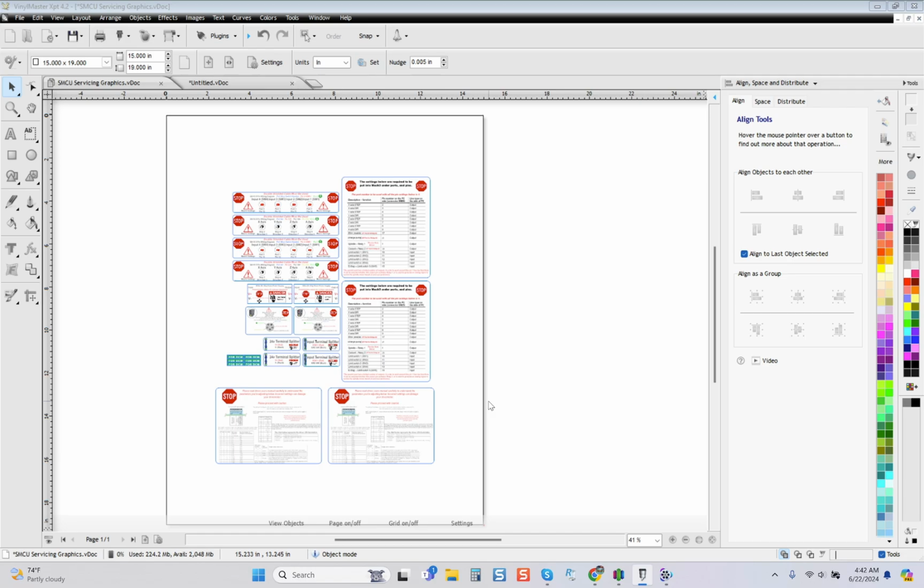It's a very, very similar process to what you'd see in a base coat, clear coat paint job for my automotive guys out there. You have the base coat and then it's protected by the clear coat. Well, with graphics, you have the base coat, which is simply printing on the vinyl. And then after the vinyl has been printed on, we then seal the vinyl with 3M 8518 glossy over laminate so that these graphics last indefinitely, essentially.